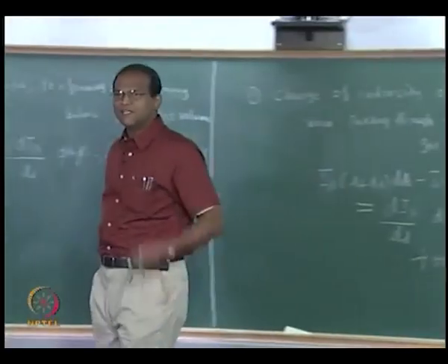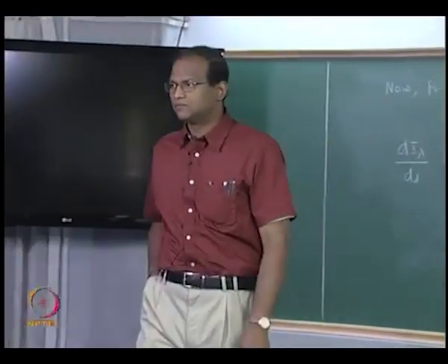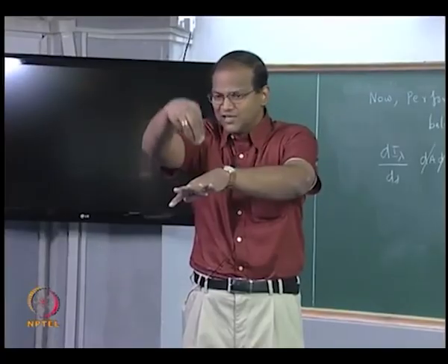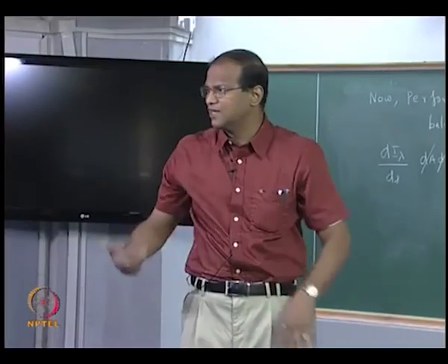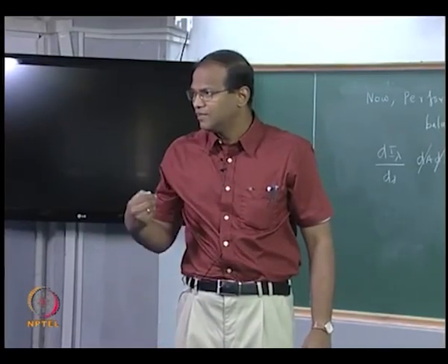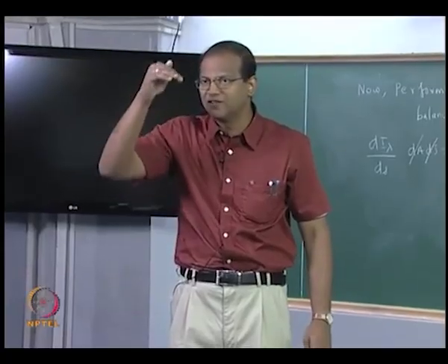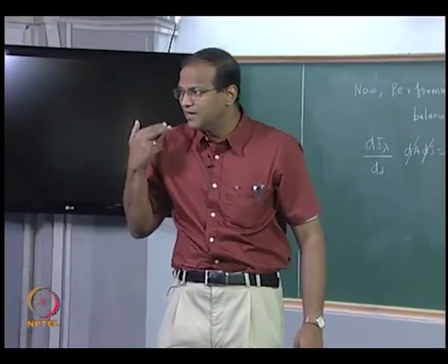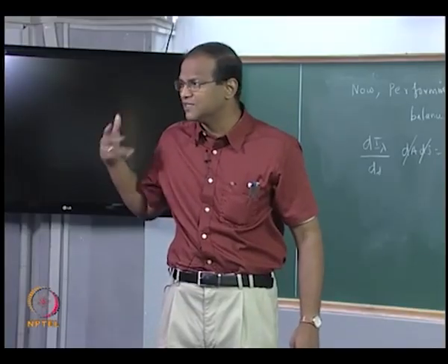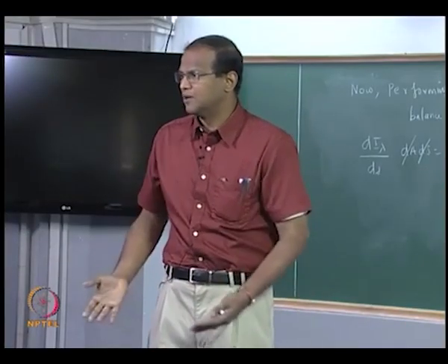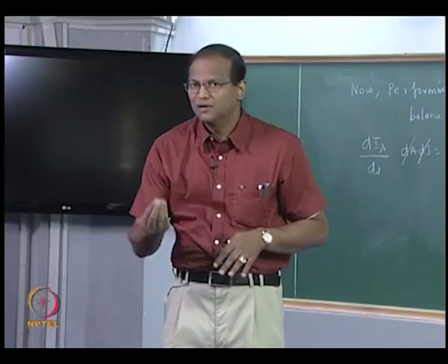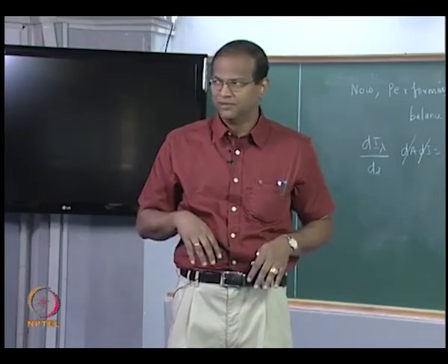When it is absorbing, I am saying that I lambda will decrease. I have a sheet of water, I am shining radiation on this. Obviously, as the radiation goes through, the bottom layers will get less radiation. In that case, what will happen to I lambda from the surface? It will exponentially decay. So it decreases the intensity which is coming out because some of it is absorbed. If 100 enter, 95 comes out, 5 is held back.